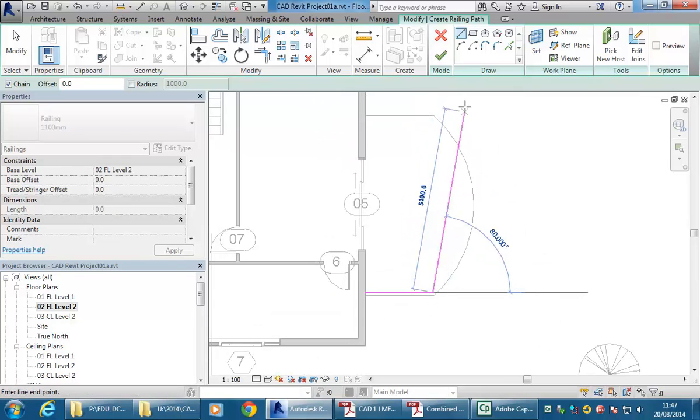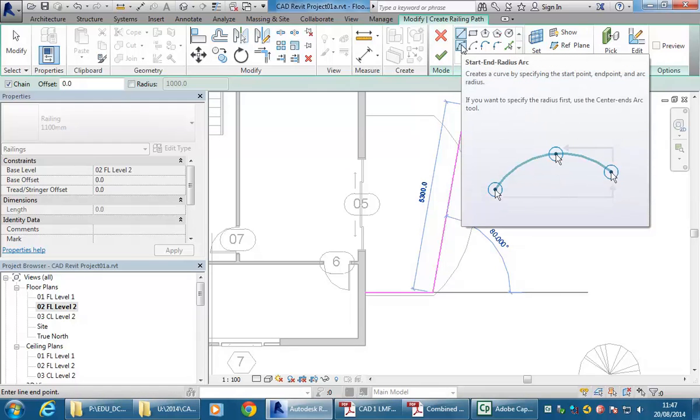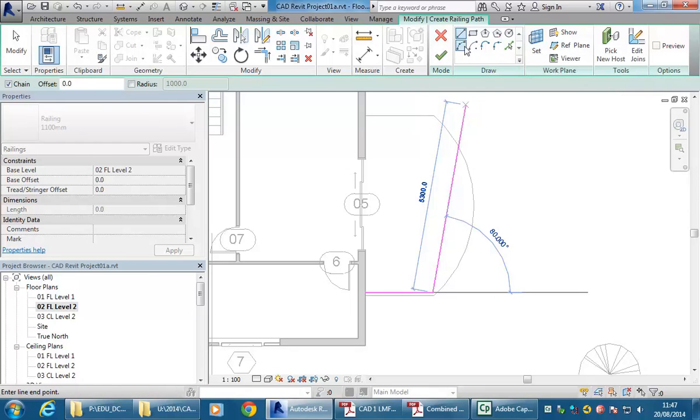Now I want a curve, so again, that first arc tool is probably the best one to try at first. The others you can use later. So with that first arc button under the line tool, then if it picks it up from the start point, you don't need to click there. And do you know why it sometimes will start or continue from the last point, and then in other cases it won't?